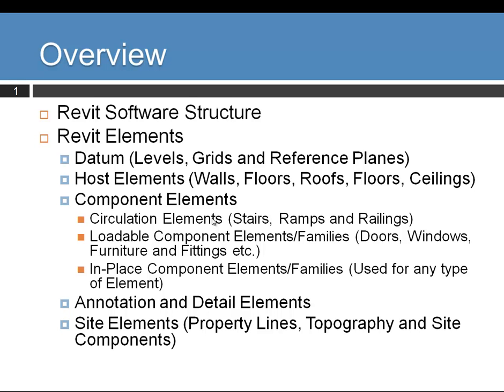Datum, we've touched on levels, grids, and reference planes. They're not all essential. Levels are the only essential one, but grids and reference planes are useful, and I'll give you more examples of those later, but we're going to look at levels right away. And then probably the thing you'd be making the most of, host elements: walls, floors, roofs, and ceilings. I put floors in there twice, I know. But we've made a couple of walls, and you might have made some floors or some roofs already.